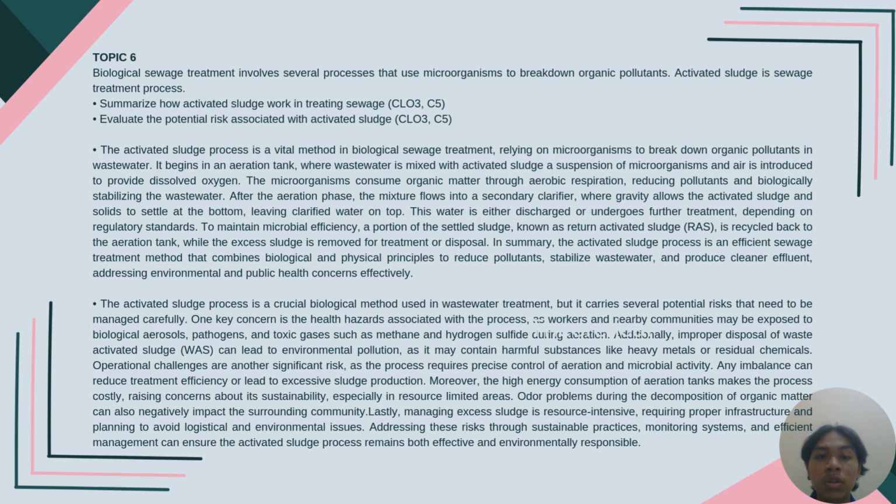To maintain microbial efficiency, a portion of the settled sludge, known as return activated sludge (RAS), is recycled back to the aeration tank while the excess sludge is removed for treatment or disposal. In summary, the activated sludge process is an efficient sewage treatment method that combines biological and physical principles to reduce pollution, stabilize wastewater, and produce cleaner effluent, addressing environmental and public health concerns effectively.